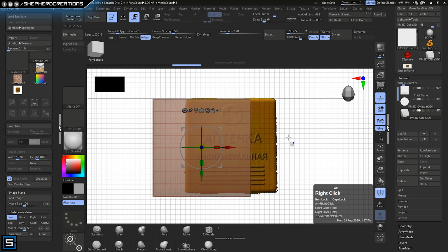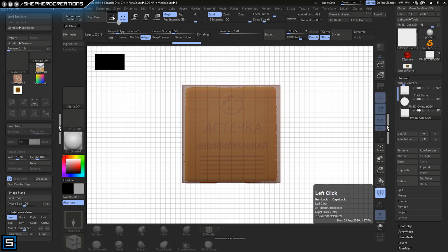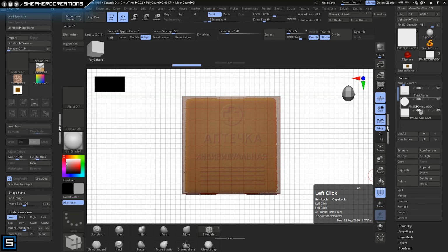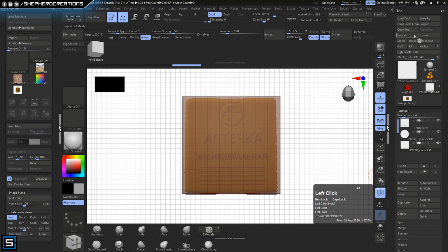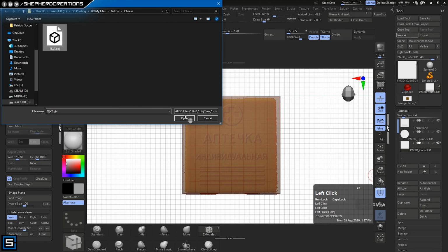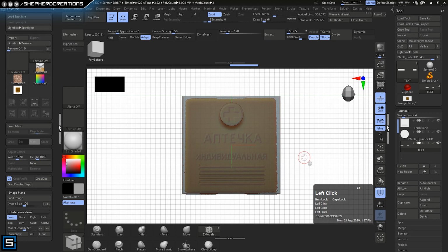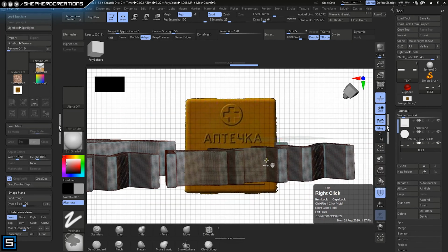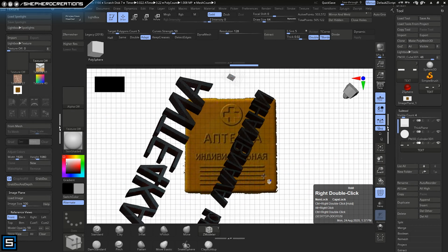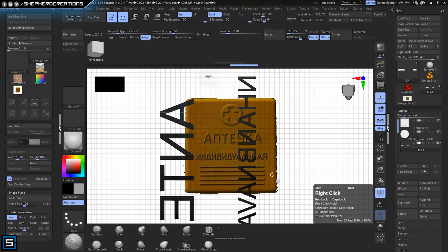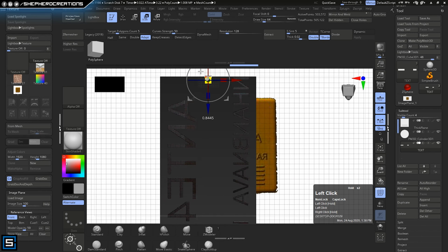You can grab out any model off of the append in the subtool list over there. All I did was go to append and select a generic model. Then I'm going to find my file when it's selected in the subtool list, and that's going to import that and replace that generic model that I had. Okay, and that's how you can import an OBJ into ZBrush.